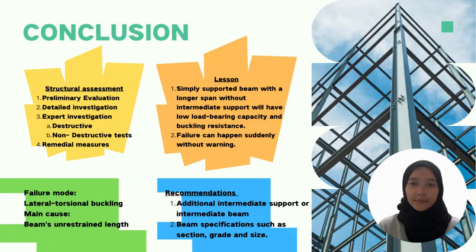Lastly, as a recommendation for buildings that may be exposed to the same situation: additional intermediate support, intermediate beam as a bracing, and beam specifications such as section, grade and size.